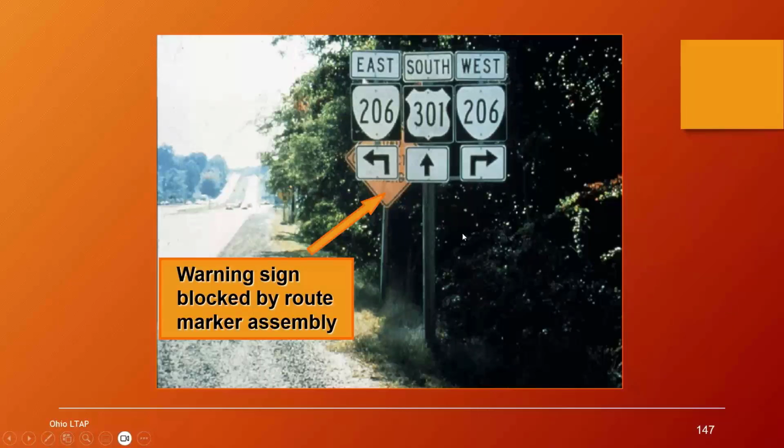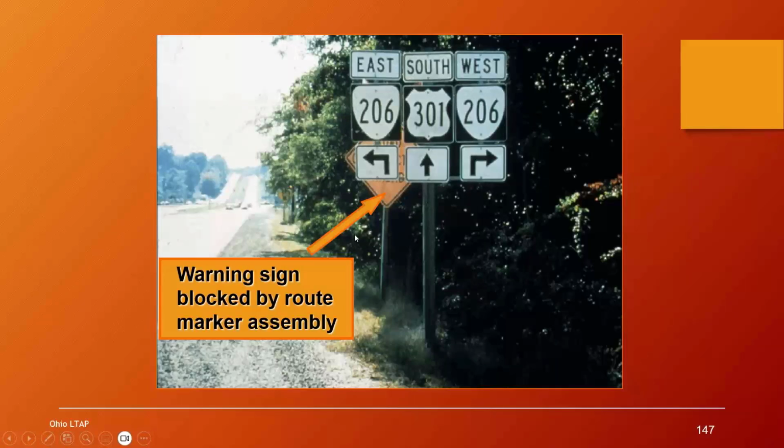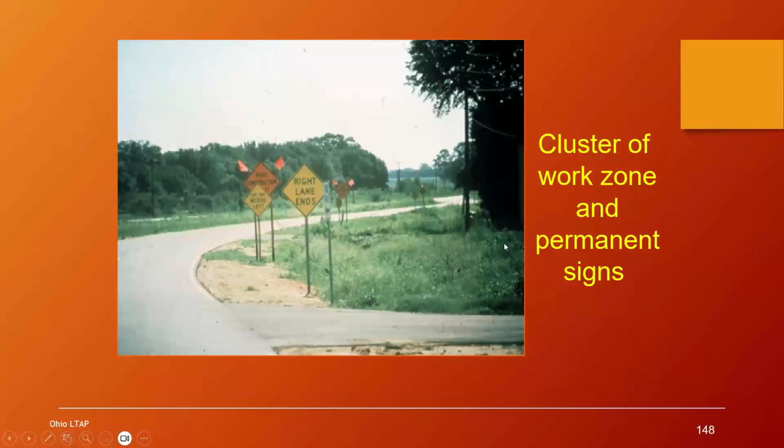And again, we need to place our signs where people can actually see them from a distance. They should be able to read your sign from at least 250 feet in advance, or even more on this highway. If you use the 4-foot by 4-foot sign, they can read it from further than 250 feet. So again, we could have adjusted the placement of this sign. You don't have to be exactly on the nose of the spacing listed in those tables. You can adjust to make sure that the drivers can see them.